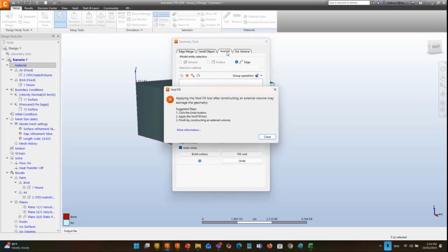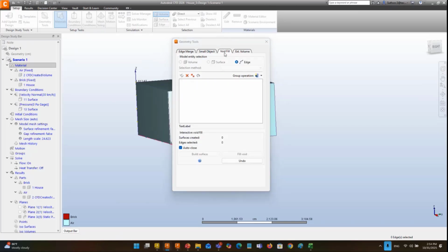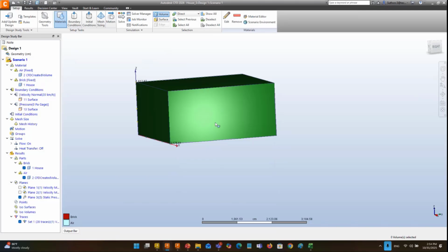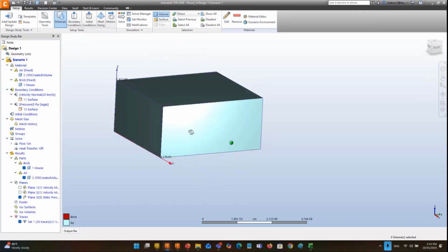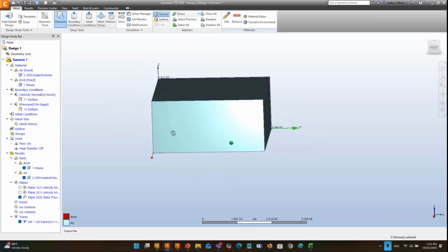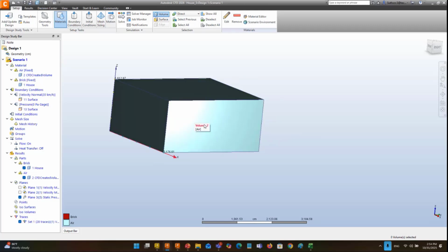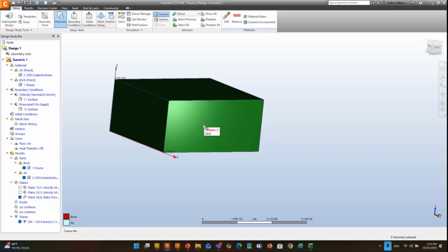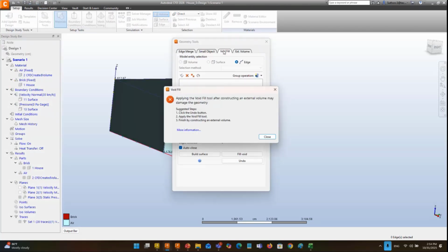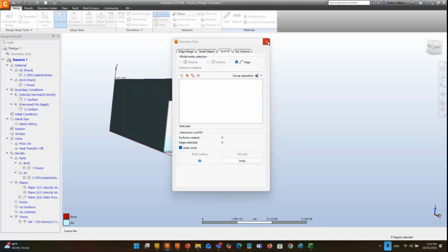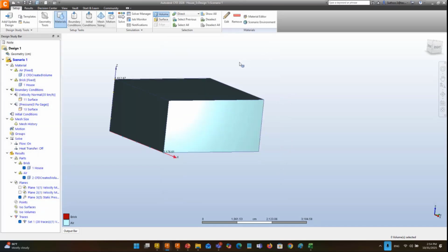For a model that has a hole, you can use the void fill to close the hole, because we want a closed system. That's our rule to remember. All the models have to be closed. It can't allow a hole to happen. For example, a valve with an open hole can't be used in our software. We have to close the hole, but we want to save your time by using our geometry tool to void fill instead of going back to the CAD software and filling the hole. Doing it in the CAD software again is quite time-consuming, right?